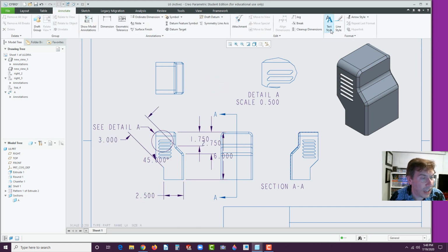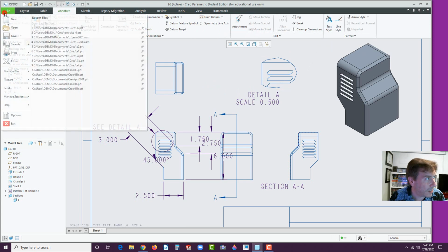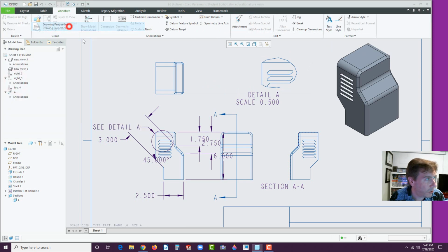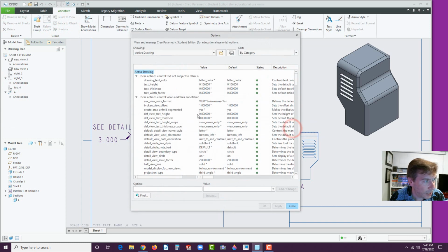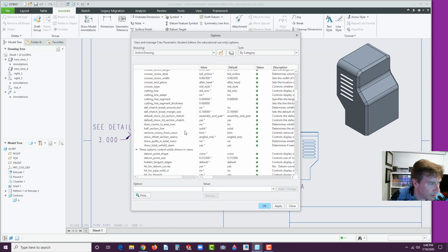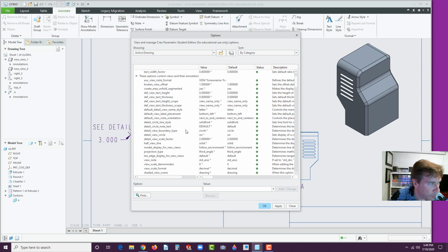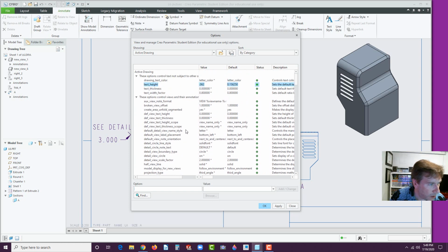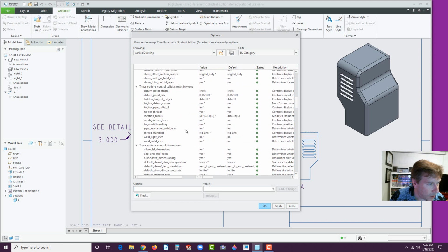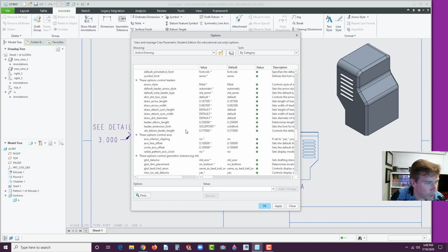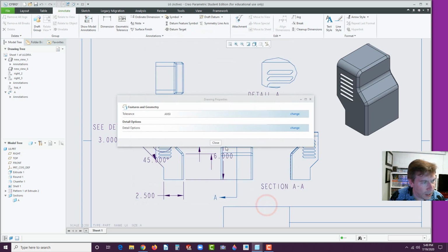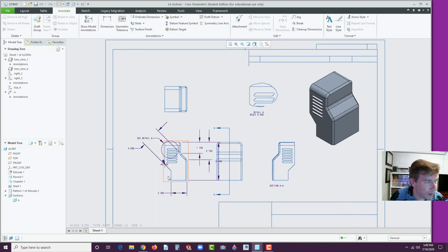Now you could go to text style and change them right here, or let's go back to the prepare drawing properties, change, and text height, click in there. Down here then, change it to 0.062. Let's see, is there anything else we might want to change that were in here? I think we're good. Let's go ahead and just hit OK and close. And then zoom in and out, and then they should appear better.